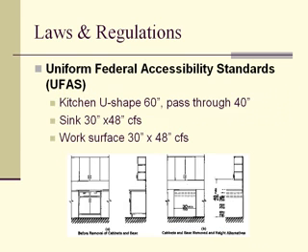Okay. When we look at kitchens, what elements are we trying to identify? If we are looking at a Section 504 kitchen, what we are looking for primarily is that if it is a U-shaped kitchen, basically enclosed on all three sides, it must have 60 inches of clear floor space between opposing cabinets, walls, and appliances. So that becomes a pretty big kitchen if you think of it. Whereas if it is just a pass-through kitchen that is open on both sides, it only requires 40 inches between opposing cabinets, walls, and/or appliances.